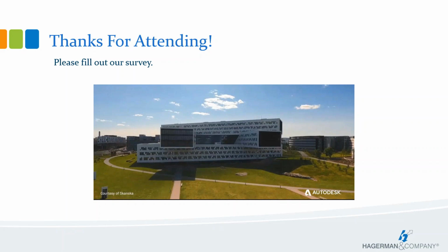Okay, so that first question there, client wanted a sloped cage ladder. Can that be done in the program? Yes, it can. Again, that would rely on the UCS. Of course, you only saw me use it in conventional matter, so it's always flat, but you can tilt the UCS so it's on an angle. As long as your Y direction is pointing accordingly, then you can create those slope ladders.